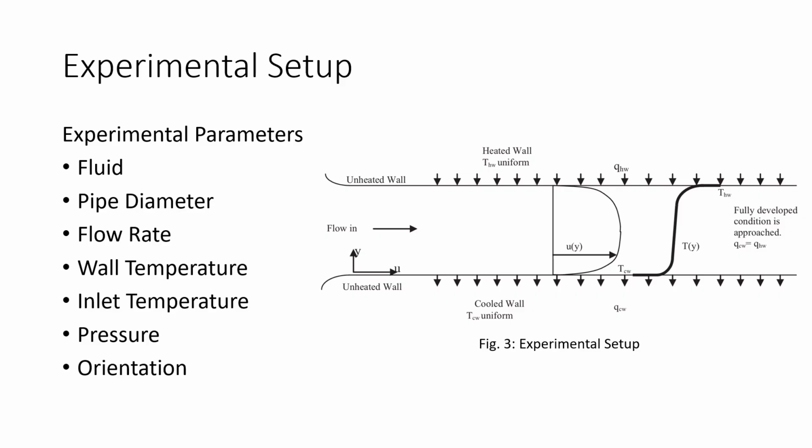What is the inlet temperature, and what pressure are we operating this fluid at? Also, the orientation of this setup plays an important role, whether it is kept horizontally or vertically. If it is vertical, then the flow is upward or downward. So all these things will decide the different forces acting on the fluid, how the buoyancy force contributes, the